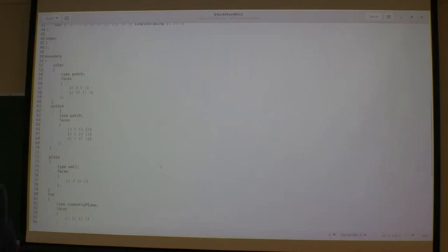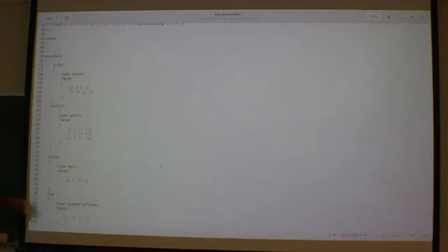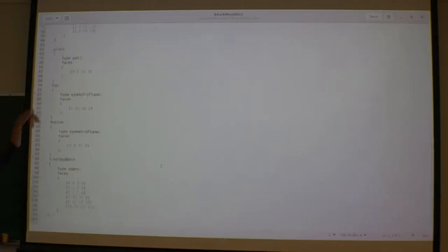So no edges, and I have inlet, 2 different inlets. Outlet, there I actually had 3, the end of each block. And the plate type wall, that's just one, the left face on the center block. And then the top and bottom are just symmetry planes, and front and back. That's it.